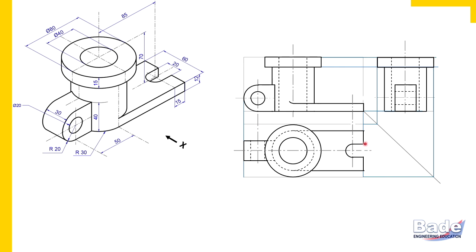Now draw end projectors. How are you going to draw the slot in the other two views? Rectangle between end projectors. Okay, so let's proceed. I have projected it, and this rectangle here is the slot in the front view, which is hidden. And when I ask you where is this slot, don't just show me this dotted line. You must know that the slot is present here. It's a complete rectangle here. This dotted line is only the boundary generator of this curved surface of the slot.